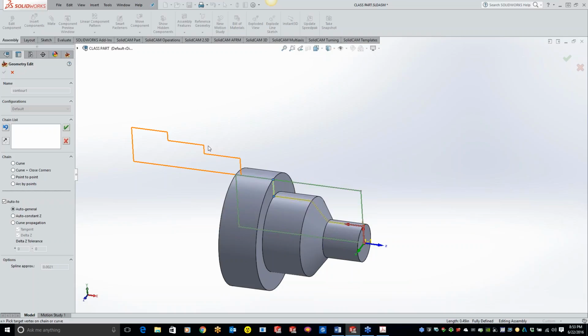You have a new question there: what font would you use for embossed letters? Anything bold. Bold is square and easy to use, but basically any font will work with embossed. Some of the fonts get into really tight little areas, so you're going to have to come in there with really itty-bitty end mills. So the best way is a bolder font, nothing real crazy, but if you need to get crazy, pick the font that looks the best. You'll just have to come back and use the rest material feature with little itty-bitty end mills to clean up those areas for you.